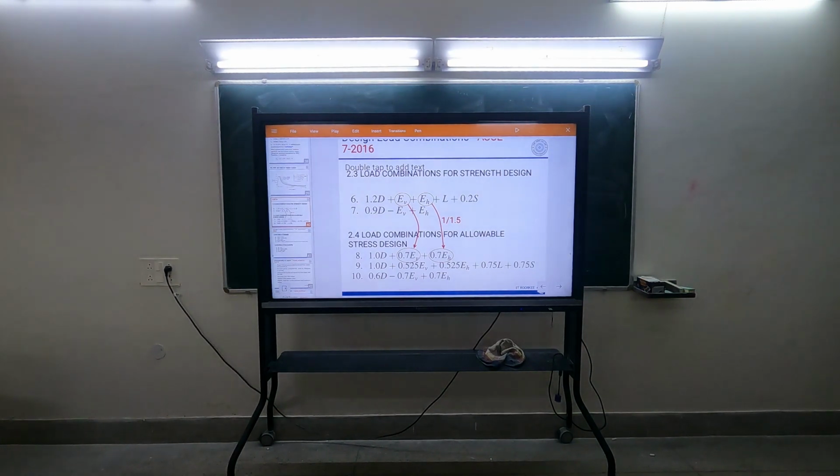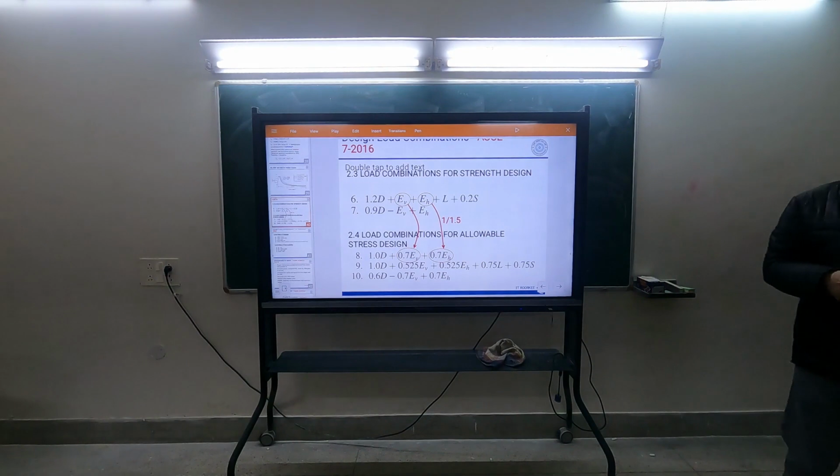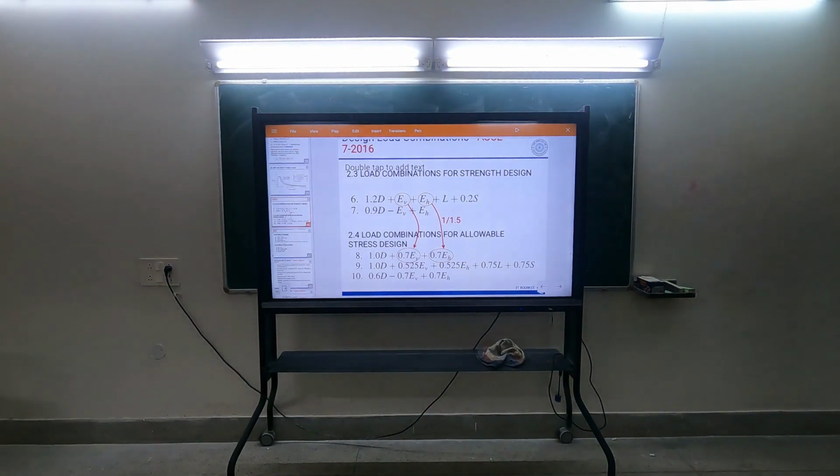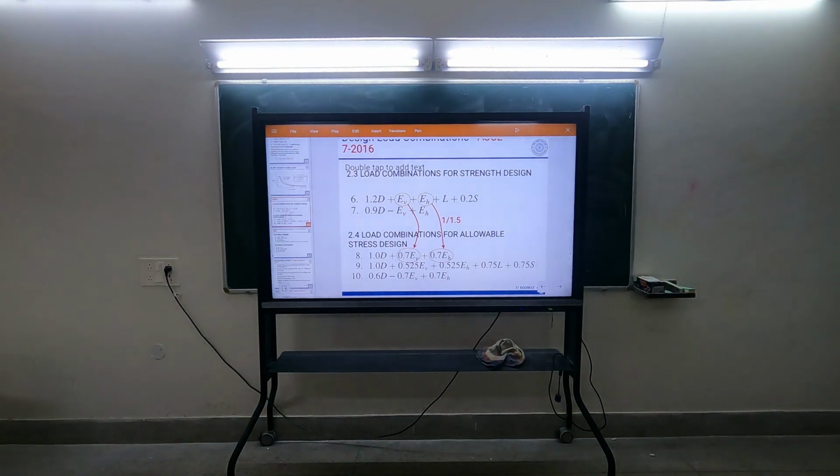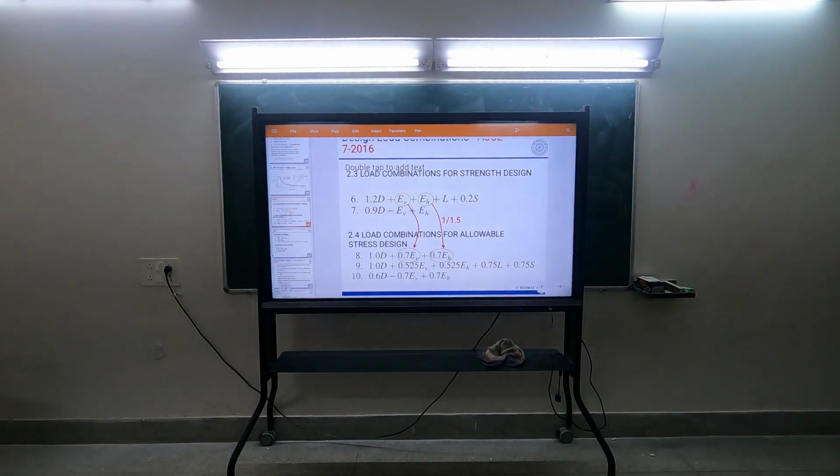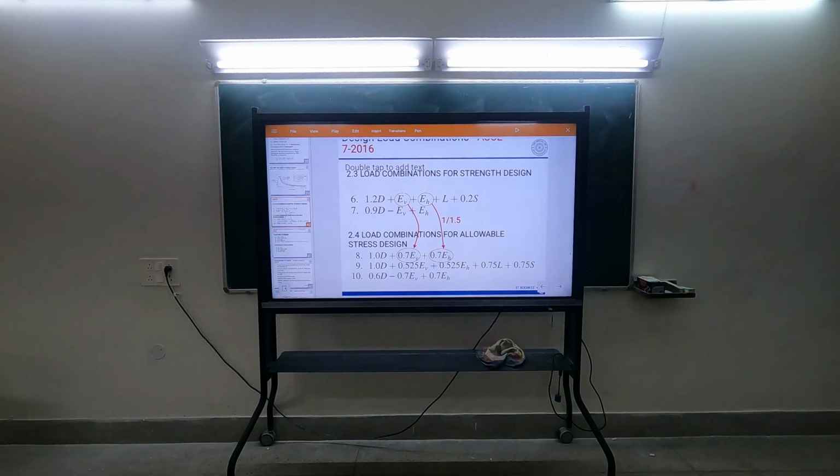In highways, it has been changed to limit state. Okay. Masonry design is still based on working stress method. Limit state method is still not developed there. So you need earthquake hazard, earthquake demand for limit state method as well as working stress method. As the name suggests, working stress method or serviceability limit state corresponds to serviceability earthquake, and serviceability earthquake is Z by 2. Yesterday we discussed. So first we calculate corresponding to serviceability earthquake, and then we multiply it by 1.5 to convert this into limit state combination.